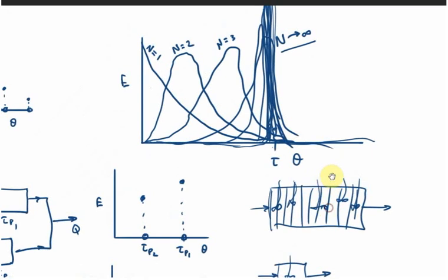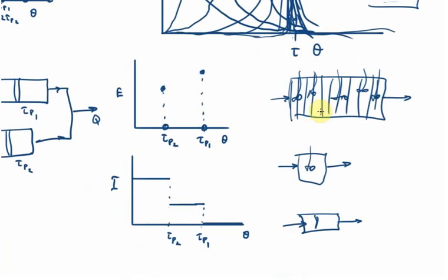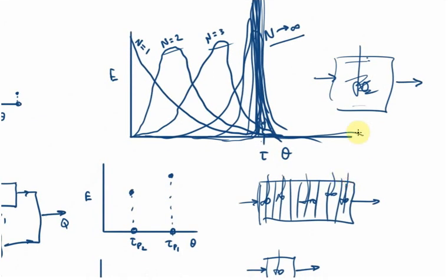And now we have a theory that allows us to approximate the real world. So if we take some real reactor, which we are mixing, but where we know there are delays because there's perhaps no slip on the wall, so it's slow there, and then we have good mixing there, but it's not infinitely fast. So the real world is somewhere between the perfectly mixed and the perfectly not mixed case. And simply by adjusting our value of n, we start to approximate this real world case. So we can regard the tanks in series model as a kind of generalization of this whole concept of mixing.